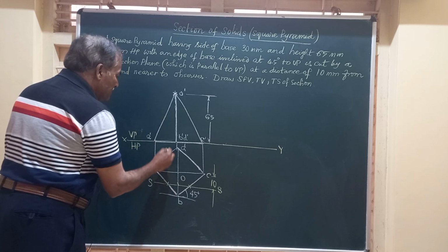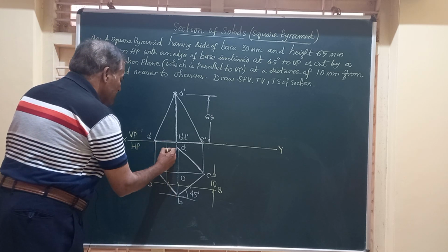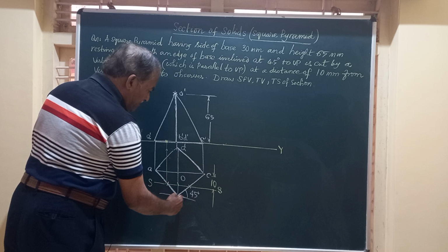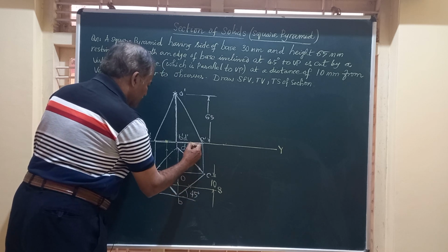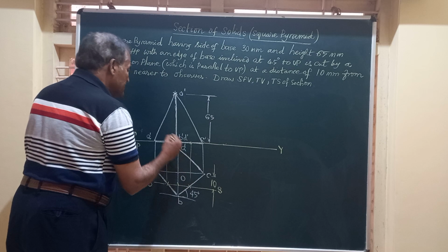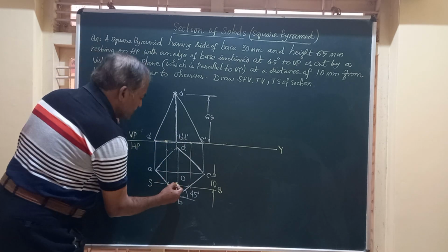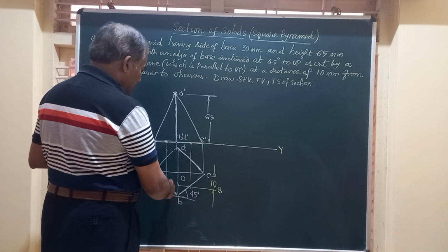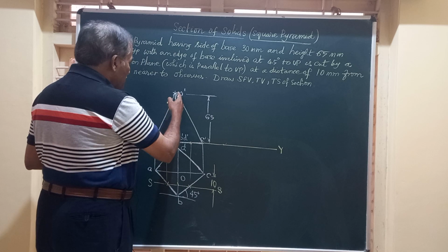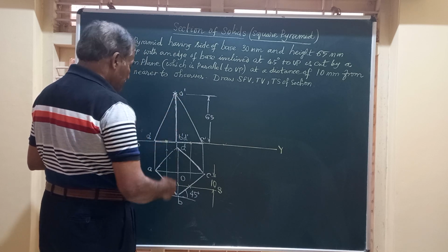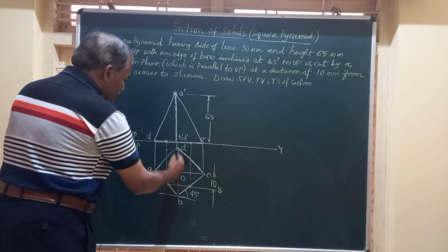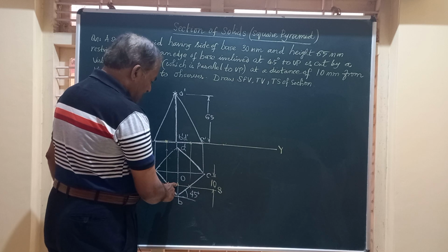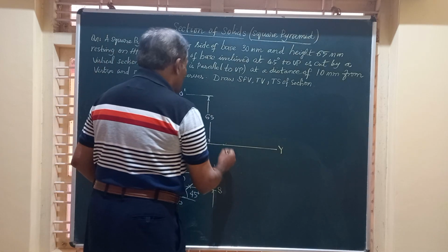It is on AB. So write a vertical line from here. It is cutting the base at this point. Similarly, on BC, it's going to be another point here at the same distance. And friends, it is also cutting this slant edge OB. But if you see here, if you see the slant edge, so both the slant edges OB and this top view, they are in the same line. Hence, to obtain this point on this OB, we are going to get